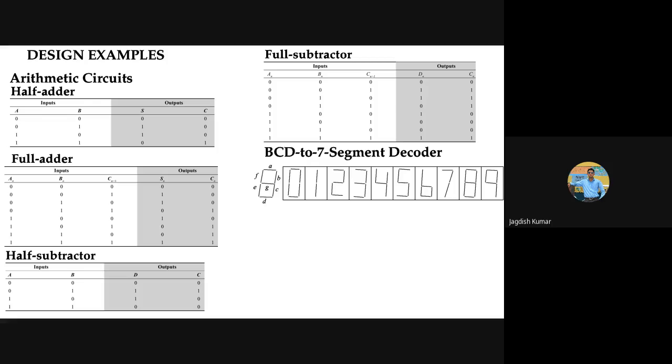They are called 7-segment displays because they can display, first of all, binary coded decimal. A BCD to 7-segment decoder. So you may have a decimal number written in binary form. I don't know whether we discussed binary coded decimal code or not. In BCD code, you reserve 4 bits for representing a binary number in the usual way, right? Like 0000 is 0, 0001 is 1.